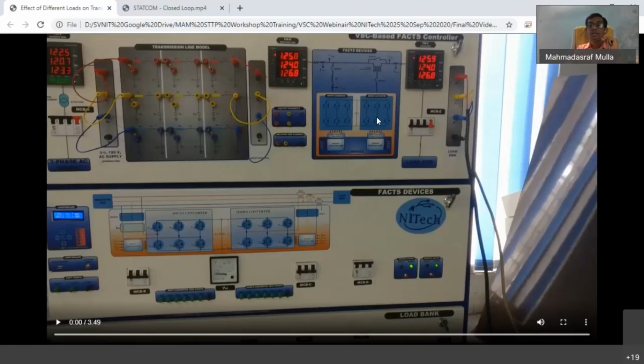So via series compensation that can be established, and the universal one is what is termed as UPFC, Unified Power Flow Controller. So you have shunt arrangement and series arrangement. Both arrangements work together, controlling the active and reactive power requirement of the load and making sure that the receiving end voltage has the required values. Okay. So this is the subject I am going to talk about.